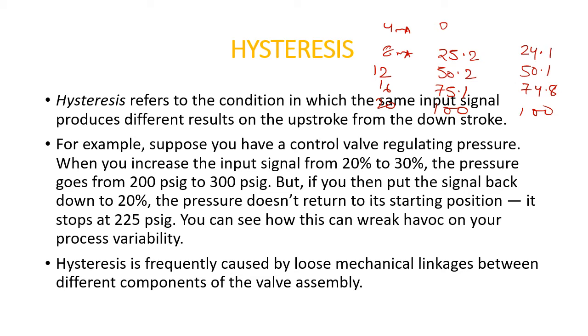So the control valve responds one way when the signal is increasing, but when the signal is decreasing the response is different. The increasing and decreasing trends are different, so that's why hysteresis is present here.